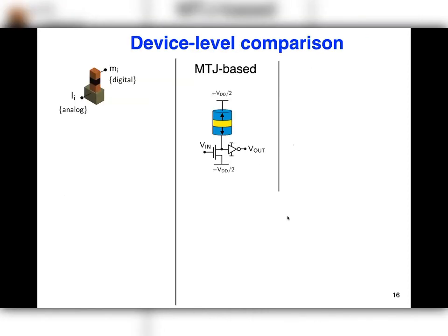Now, in these last two slides, in the last 2 minutes or so, I'll show you a comparison, a detailed understanding of why we think good hardware for p-bits is important. I've shown you this MTJ-based p-bit that gave you complex functionality. The first question you may have asked is, how do I do it with CMOS? MTJ seems like an exotic emerging technology, even though it's been scaled up to 1 billion bit densities. Why do I not do this with CMOS? Now, you can, and we've done it.